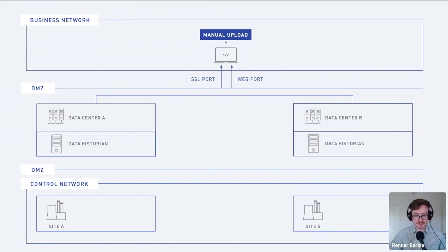In my experience, the Purdue model does not scale well in terms of complexity. And this is because as you increase the number of data sources you want to share and increase the available audience, the more potential risk you start to accumulate. So then you need to add additional security hardware and make your networks even more complex. But then that added complexity itself starts to constitute its own security risk, which is what you're trying to avoid in the first place. So very quickly, you can get caught in this feedback loop and be stuck in a losing battle against entropy.